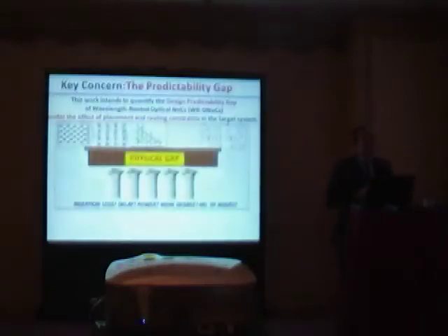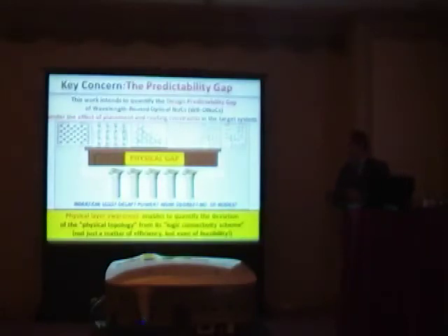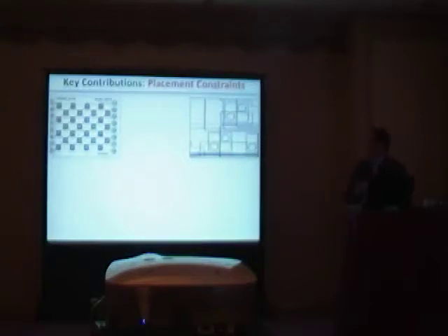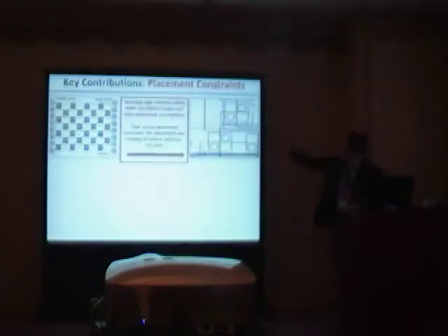In fact, there exists a physical gap between an appealing logic topology and the corresponding physical one in terms of insertion loss, delay, and power, and so on. Moreover, physical layer awareness is certainly a right way to quantify this deviation, but not just to identify if a specific topology is better than another one, or is more efficient than another one, but even more important, to identify its feasibility.